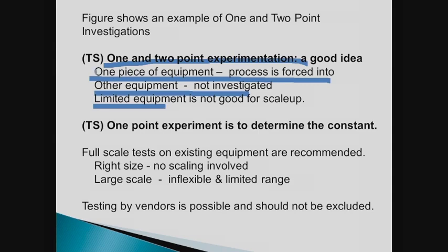See, that's the problem. You got stuck with one piece of equipment. The process is forced into that one piece of equipment. The other equipment has not been investigated. The geometry is the most important variable, and you're not studying it. Limited equipment is not good for scale-up.